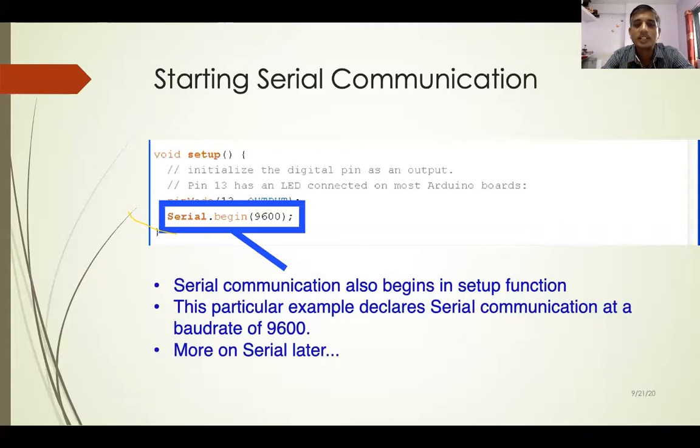For serial transmission and for serial reception, separate lines are available, just like your RX and TX line. If both separate lines are available for this, then that type of communication is called a full duplex type of communication. Getting? So to start the serial communication in your Arduino is very easy. You just need to mention the baud rate. Now we will discuss the baud rate.